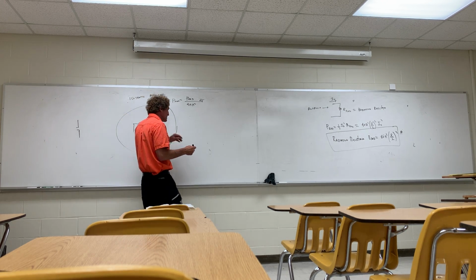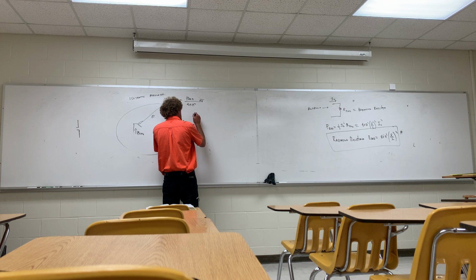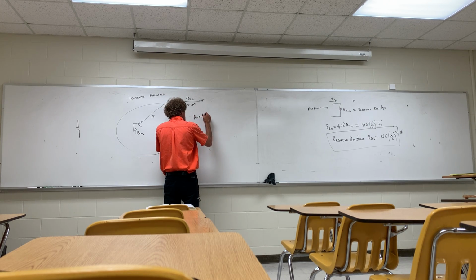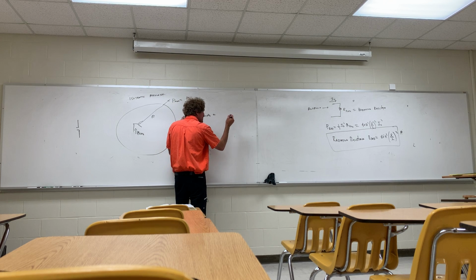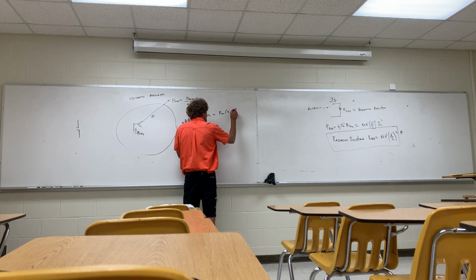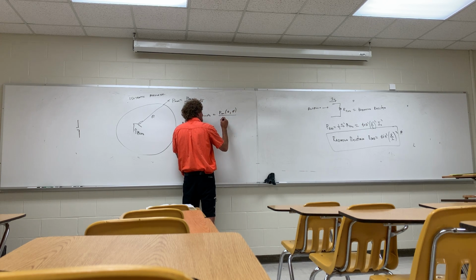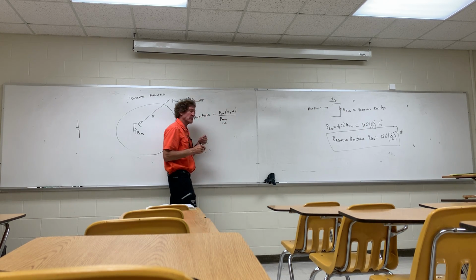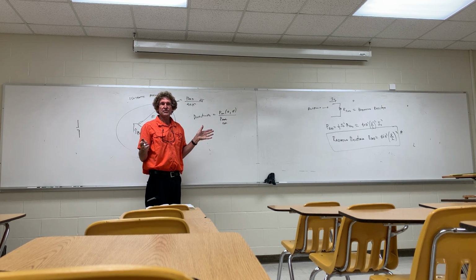radiator. So the definition we talk about, when we talk about directivity, is really the average power density, or Pav, by our antenna as a function of phi and theta over the power average that would be for an isotropic radiator radiating the same amount. So if you think about it, it's going to give us a value that should be greater than 1 at some point. It should be a lot greater than 1. Do you all follow me on that?